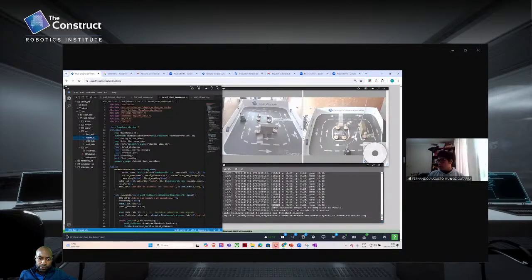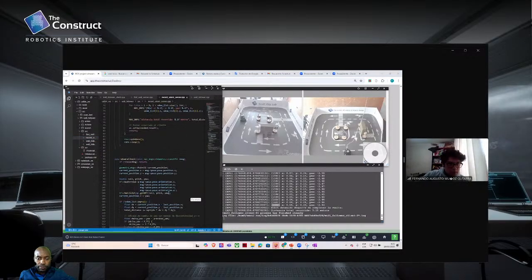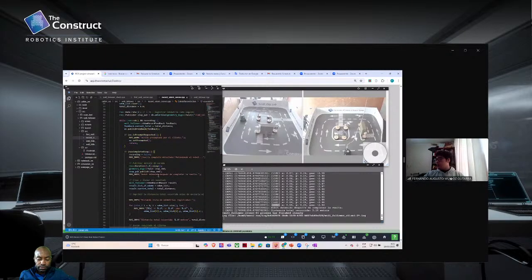First, we create the action server configured with the name record odom. It subscribes to the odom topic to receive the odometry and records odometry every second. In this part, the most important function is that all the feedback is published to the client with the accumulated distance.